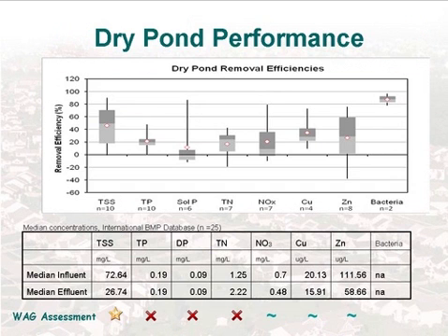And I think you could see through the plot of these removal efficiencies, it reflects that compared to what you would see for a wet pond, aside from total suspended solids, it has a little over a 40-45% pollutant removal efficiency. The other pollutants don't do that well, and there's quite a variability in the data itself. So looking at the median influent and median effluent concentration from the International BMP database, you'll see similar patterns by looking at the actual numbers versus the box and whisker plot.